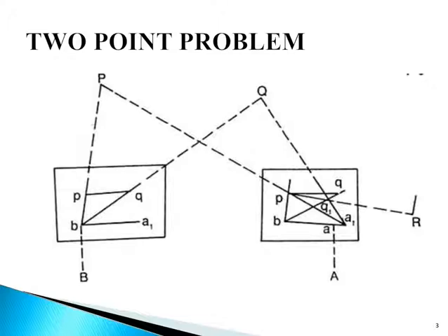An auxiliary station B is selected at a suitable position. So here station B, capital B, is there. The table is set up at station B, labeled, and oriented by eye estimation, and then clamped. With the alidade touching small p and small q, the points P and Q are bisected and rays are drawn. Suppose these rays intersect at point B.